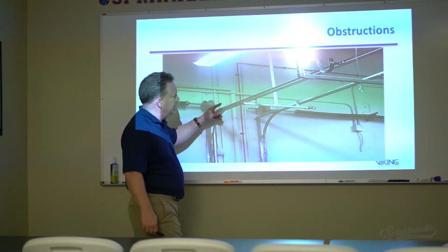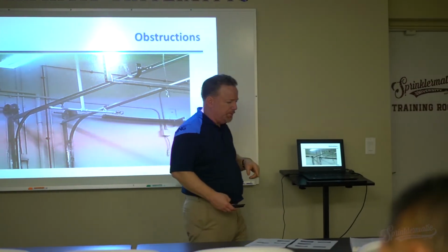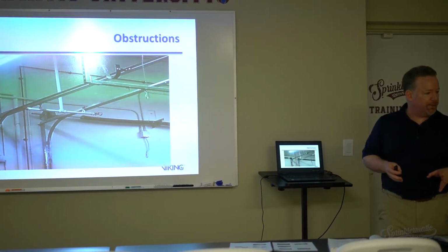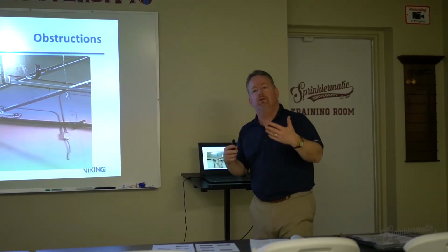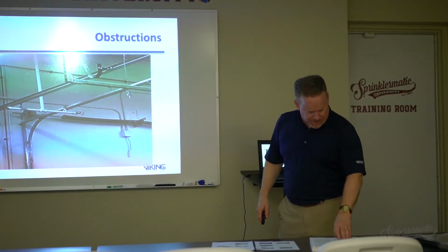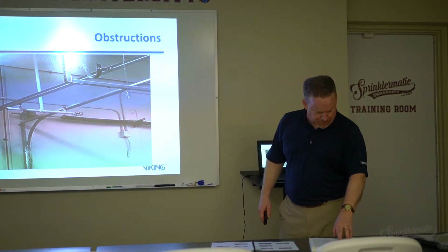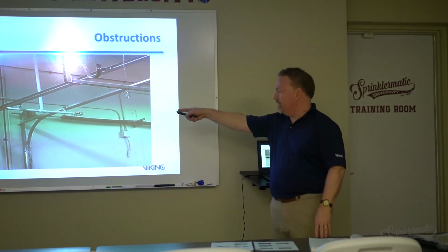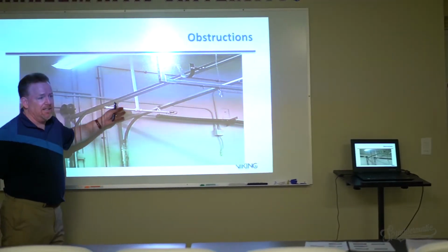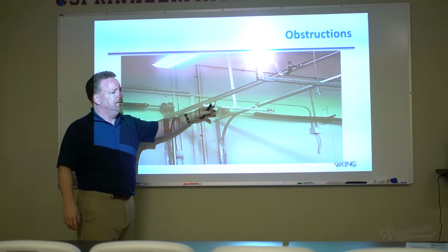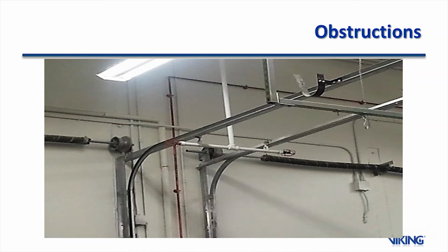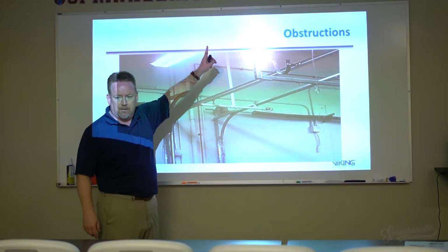Now in some cases, and this is one of those things where, remember, I read out specifically the general rules about sidewall sprinklers. And we said you can put them under what? We can put them under flat, smooth ceilings, right? And in light and ordinary hazard occupancies. And then it is to protect areas below overhead doors. Specifically right here. So these look like they're really far down from the ceiling line, and that's true. But once I open these overhead doors, what's obstructed? All my ceiling sprinklers are now obstructed from above.